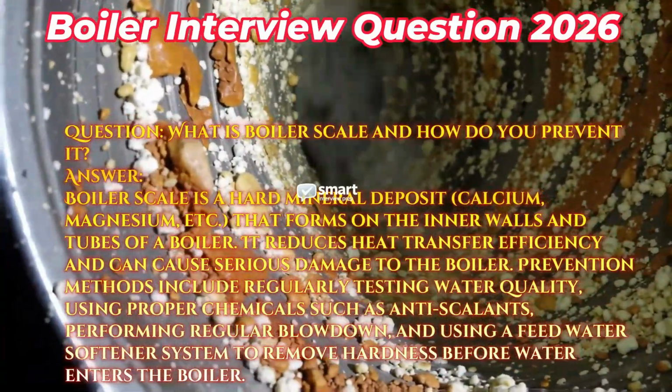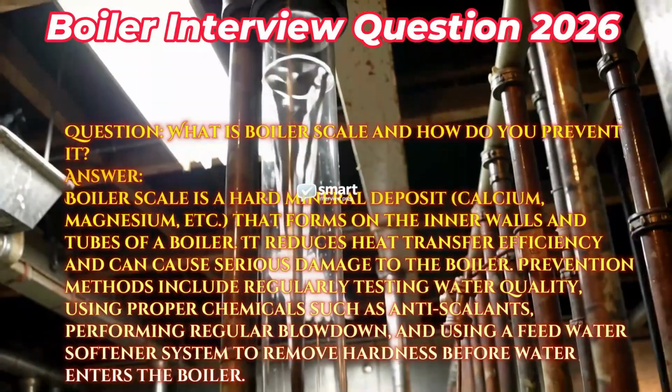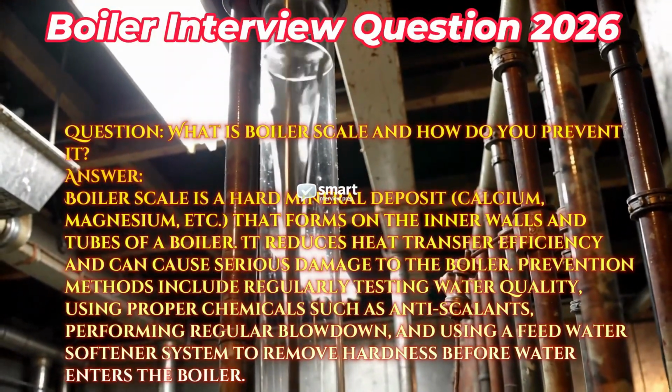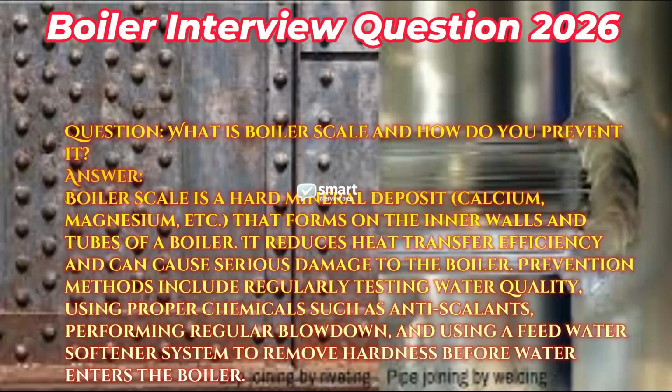include regularly testing water quality, using proper chemicals such as antiscalants, performing regular blowdown, and using a feed water softener system to remove hardness before water enters the boiler.